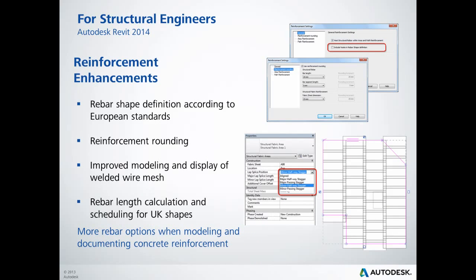There is a new feature in the reinforcement settings called Include Hooks in Rebar Shape Definition. With this new option, hooks do not influence rebar shape. This improves definition of rebar shape codes according to European standards and extends structural workflows into the fabrication process.